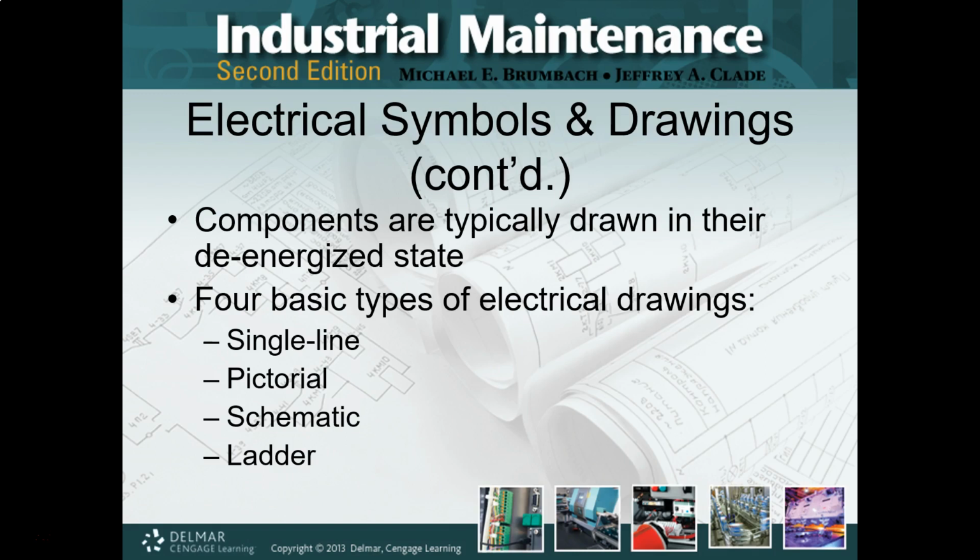Now, once again, it doesn't show how they're terminated, where the wires go to what location. It just shows the wires going to the component. That's it. If you want to see where the wires are going, specifically where the wires are being terminated, hooked into the component, you're going to either need a schematic or a ladder diagram.